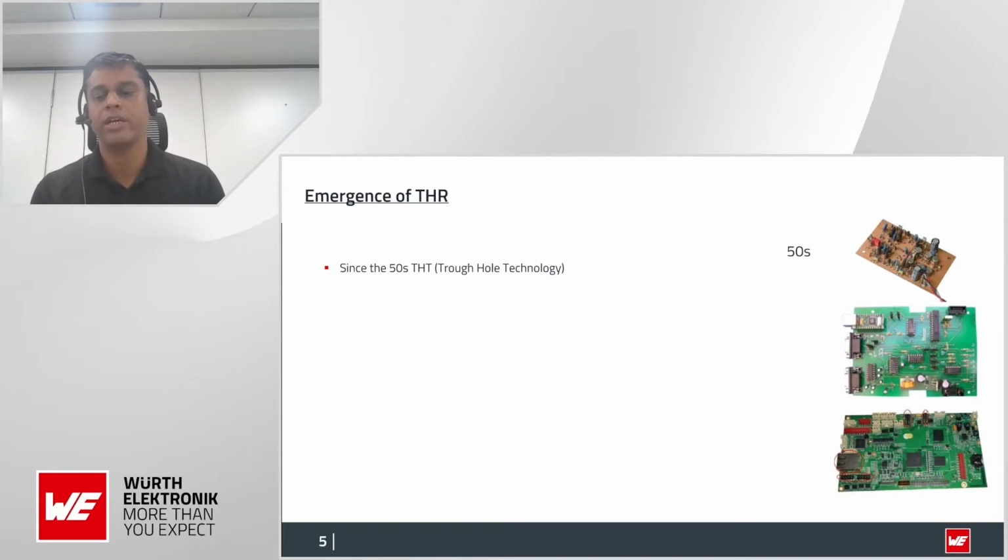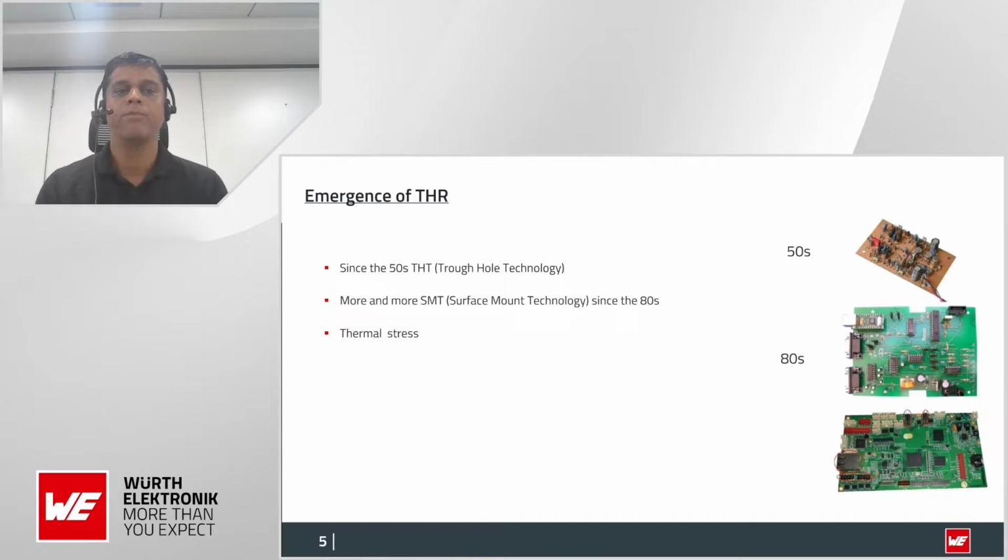As the market evolved and more technology came into the picture, we came up with small components, and the density of components on the PCB increased. So the surface-mount component came into the picture, where we can assemble the component with the reflow process, and most importantly, we can use the PCB on both sides, top side and bottom side, which was not available in the wave soldering process. But when we talk about this, thermal stress came into the picture.